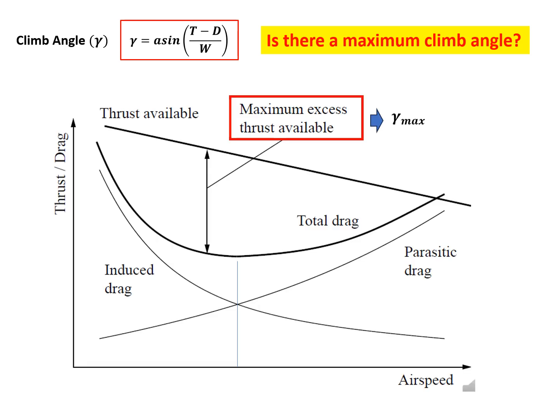We know the thrust decreases with the speed of air, as you can see in this graph. Regarding the drag, it has induced drag and parasitic drag. According to the graph, although we will show later how we can get this graph, the induced drag decreases with airspeed, but the parasitic drag increases with speed.